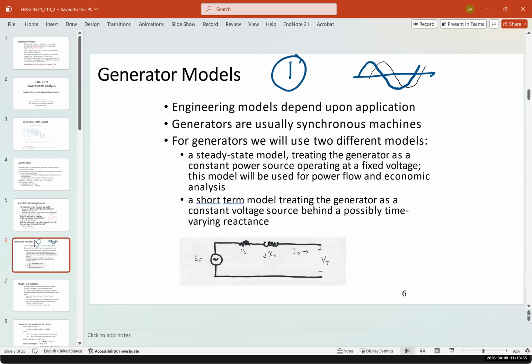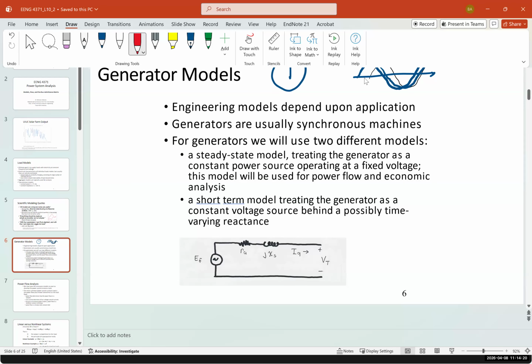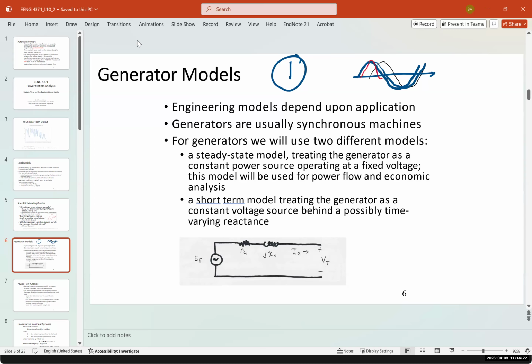So do you know how we synchronize the generator with the grid? How can we do that? Speed the generator up. Yes, perfect. We can speed up the generator. Actually, we alter the frequency, and we would speed it up or speed it down until we can match this.